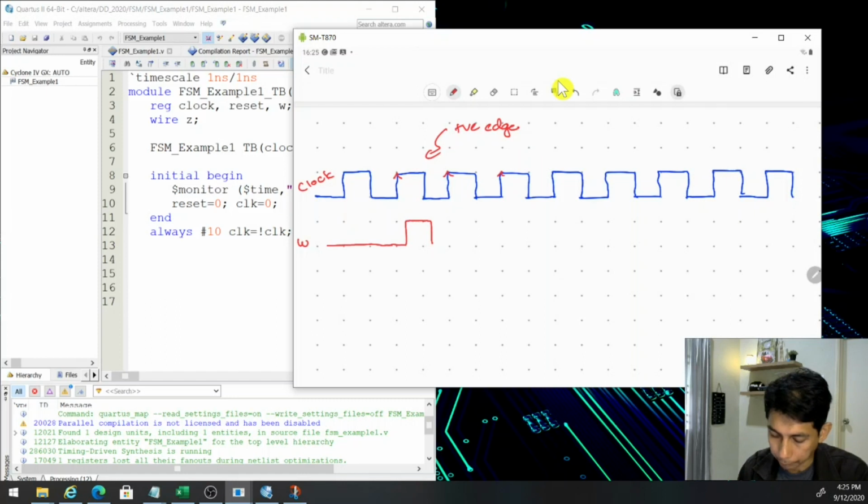And when we have a signal like this, it means our system reads this as 0, because w is so short that our system cannot detect it. At the next positive clock edge here, the signal is already 0. So the first clock edge is 0, and the next clock edge is 0 already. So this is considered a false signal, not counted as w equal to 1.